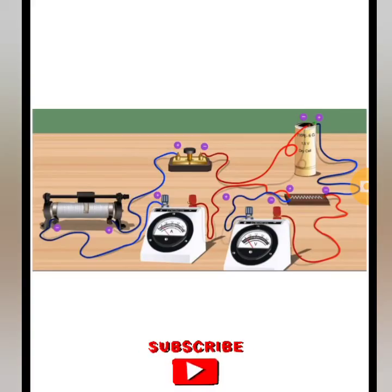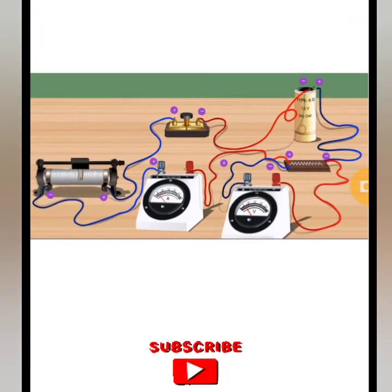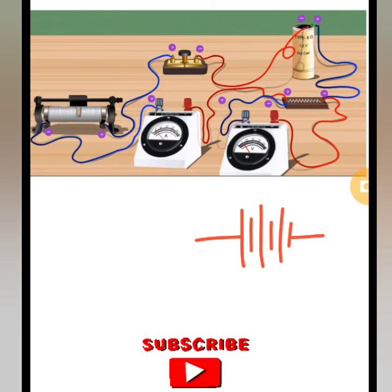So now you know all the circuit symbols for the circuit components. Let's draw a circuit diagram for the circuit shown here. You can see in this circuit you have a switch, a resistance, a rheostat, an ammeter, a voltmeter, the battery and connecting wires. So let's start drawing the circuit by first drawing the battery. You can see that a resistance is connected from the positive terminal of the battery. Draw the resistance in the circuit.